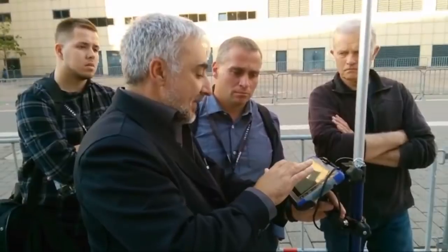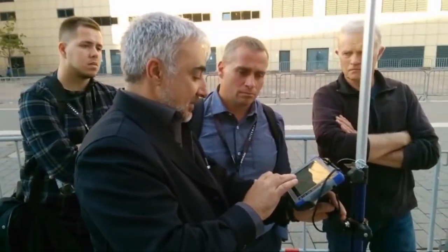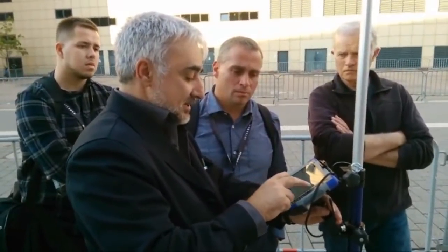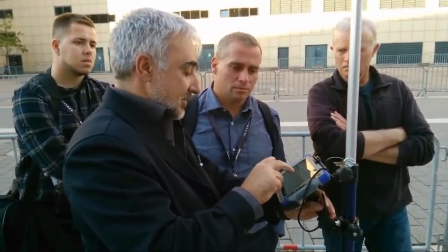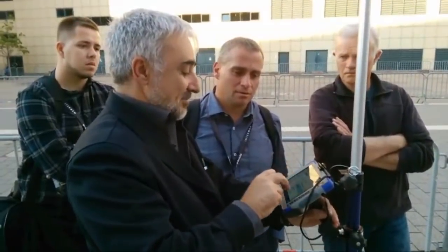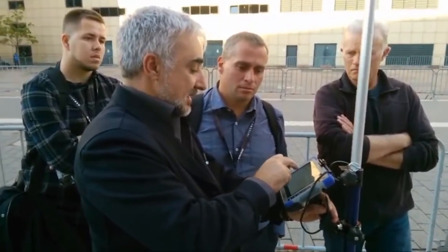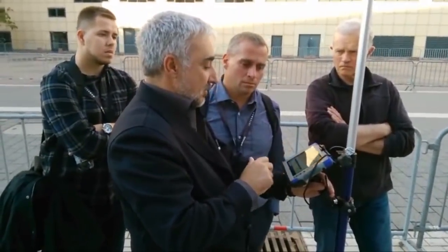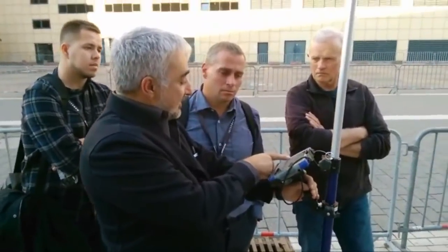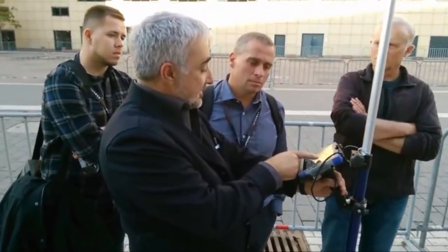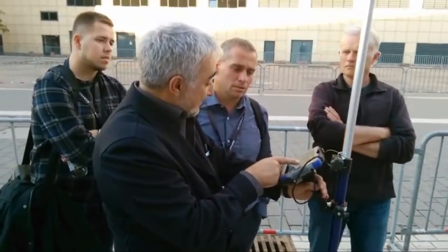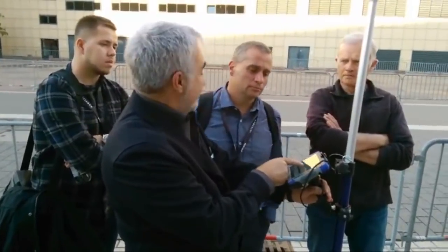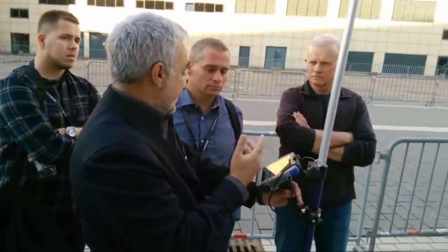Let's put a very tight tolerance in hybrid. Instead of 4 centimeters, let's say 0.001 millimeter. What happens if I try to store points, measuring with the total station? Oh, warning! Hybrid tolerance exceeded, vertical residual of 16 millimeters. That is the one I got, exceeding the tolerance of 1 that I had set. Continue, yes or no?